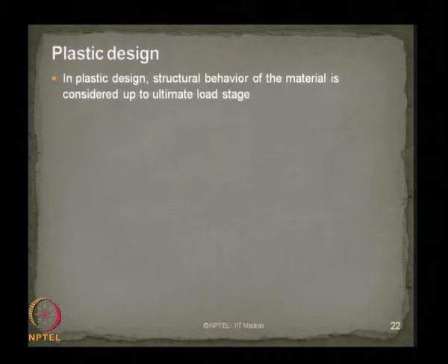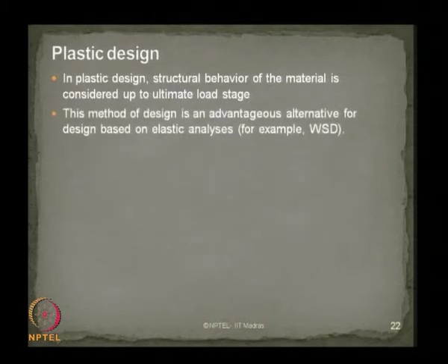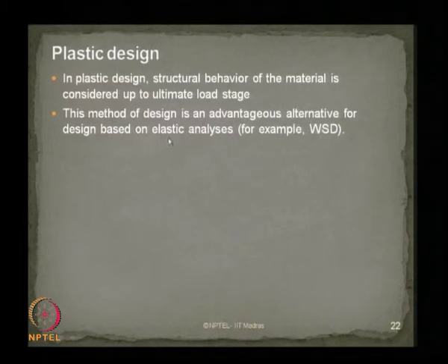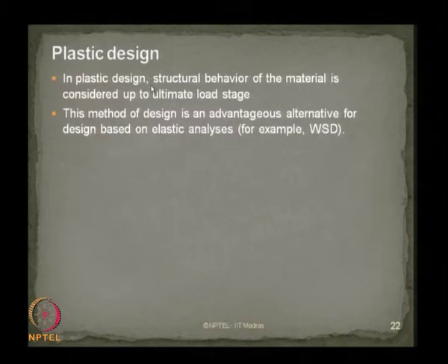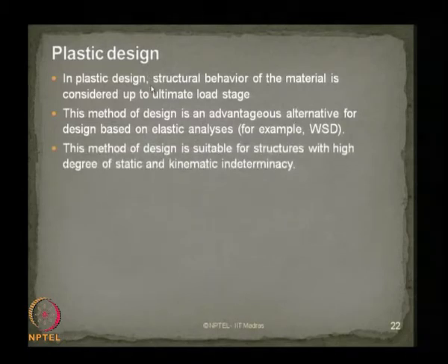In plastic design, the structural behavior of the material is considered up to the ultimate load stage, whereas in LRFD this was not true. This method of design is advantageous because it is a very good alternative to the design procedures suggested by working stress design, because working stress design uses elastic analysis, whereas plastic design uses plastic analysis. This method is highly recommended for structures with a high degree of indeterminacy.